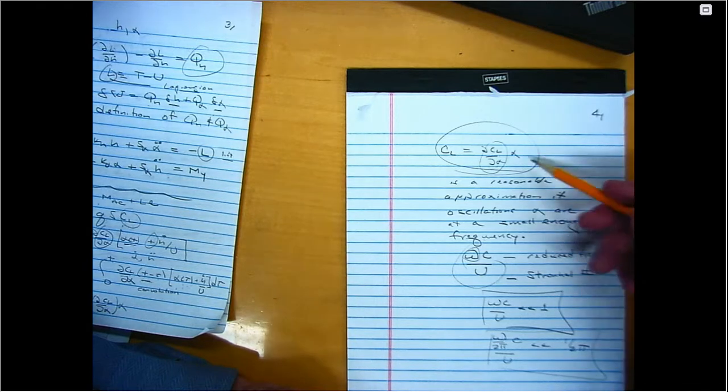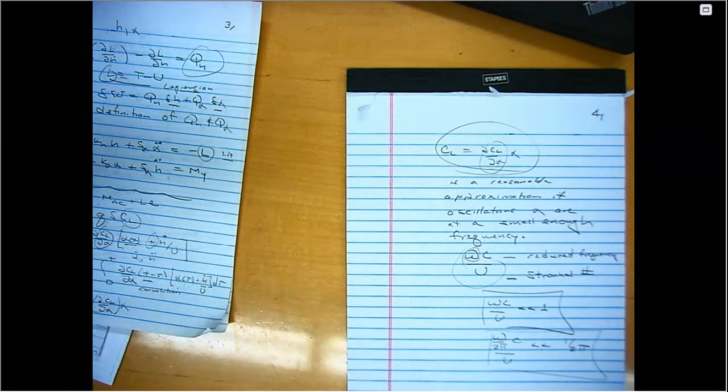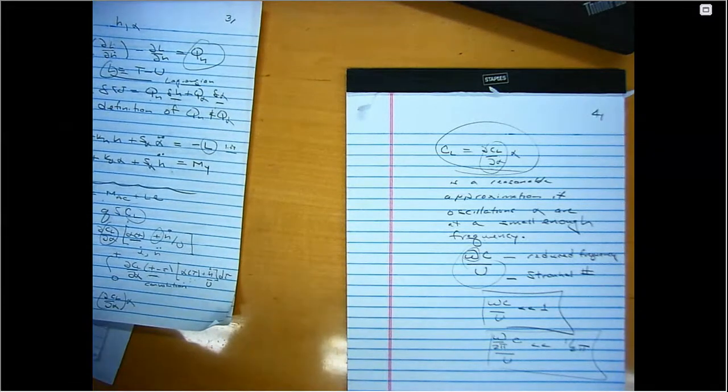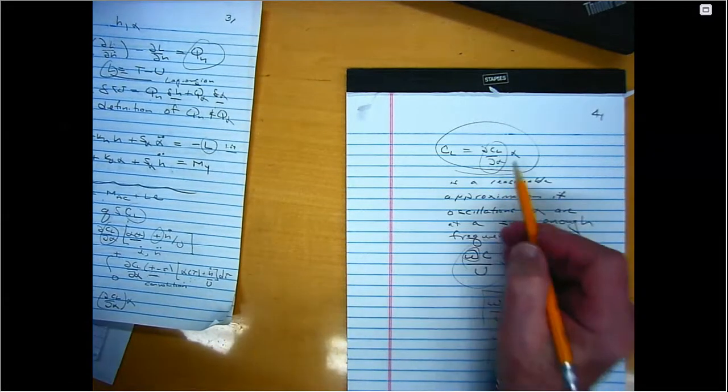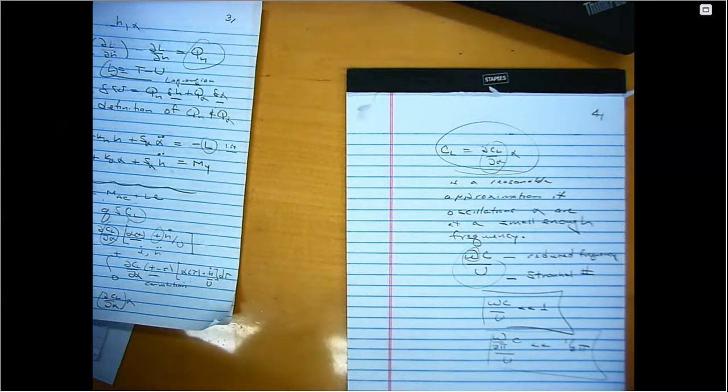So when you use this model for the aerodynamics, among other things, you'll be able to compute the reduced frequency after you've done the flutter analysis. And you can find out whether it's small enough or not. If it is, you say, great, I had a good day, I'm going to go home. If it's not, if the reduced frequency that you compute from the flutter analysis using this model is high enough, you say, I got more work to do.